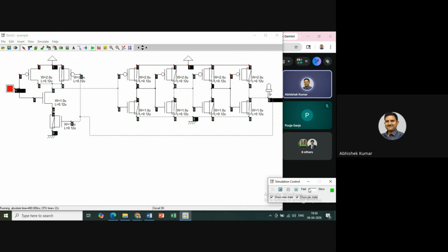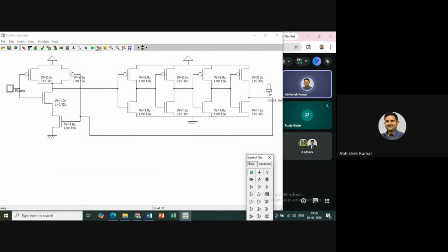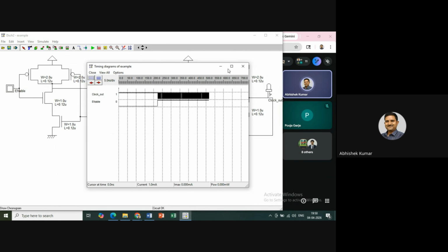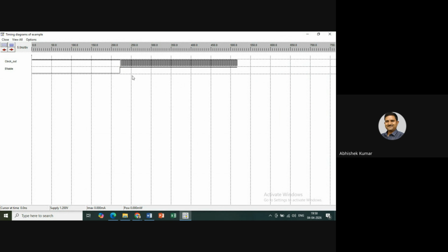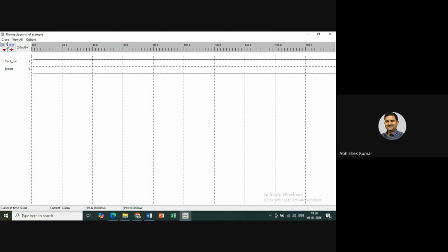I can show you here the pin state. It will display what the values are. I'm going to make the simulation speed slow, so that I can have this type of connection. As I displayed during the discussion, 0 1 0 1 will appear after some delay. That is going to provide an oscillation. Okay. So now I'm going to stop the simulation and you can visualize it in the waveform. You will have this type of output waveform. I'm going to zoom it.